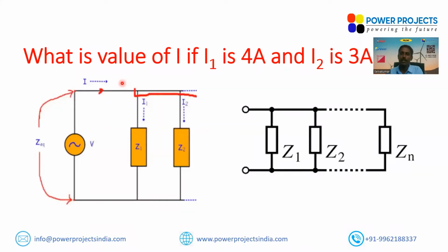It looks very basic, but I have seen so many legends in amazing power system consulting companies directly adding this current with that current. In Excel, adding is quite simple and easy, right? But we forget a very small basic that changes the entire equation. They conclude that the transformer is insufficient or the generator is insufficient, but in reality it could be more than enough. All right. So whenever you have two different currents, or loads connected in parallel, ensure that you always add a vectorial sum, not a direct sum.